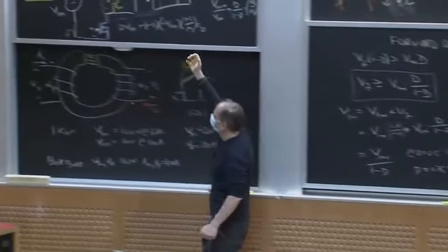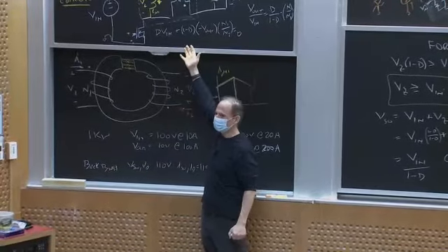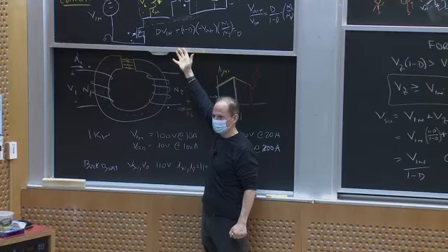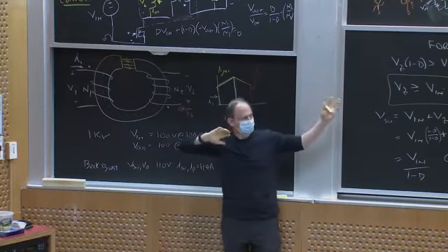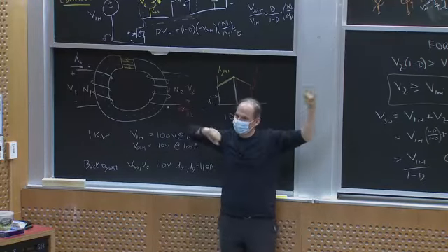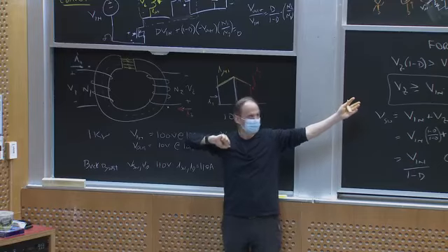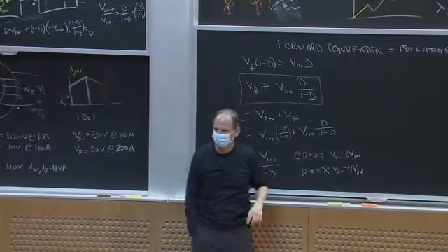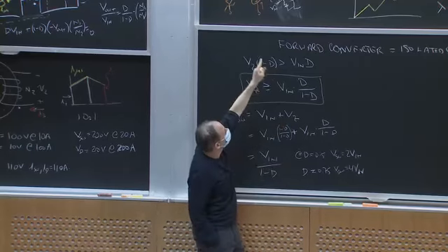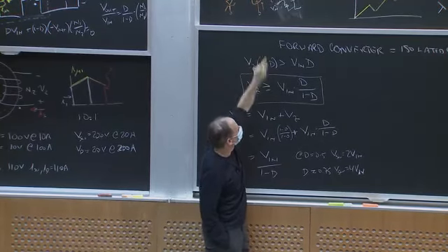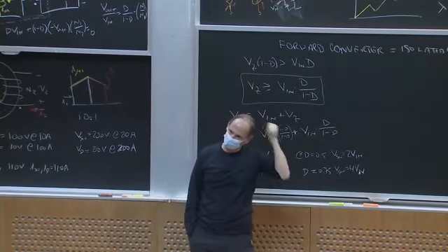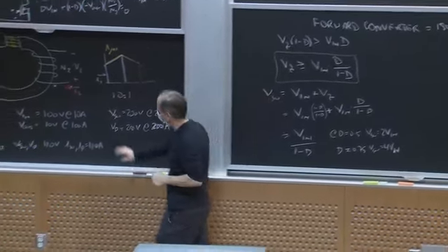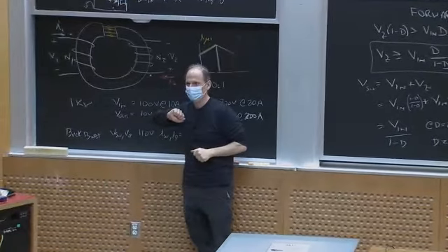The flyback converter is based on an indirect topology which has lots of energy storage. So it turns out that depending upon the design regime, a forward converter can actually be a lot smaller because, keep in mind, this transformer doesn't really need to store any energy. The only real energy storage element, which is the size limiting element, ought to be that inductor. And that inductor is smaller than this flyback transformer.